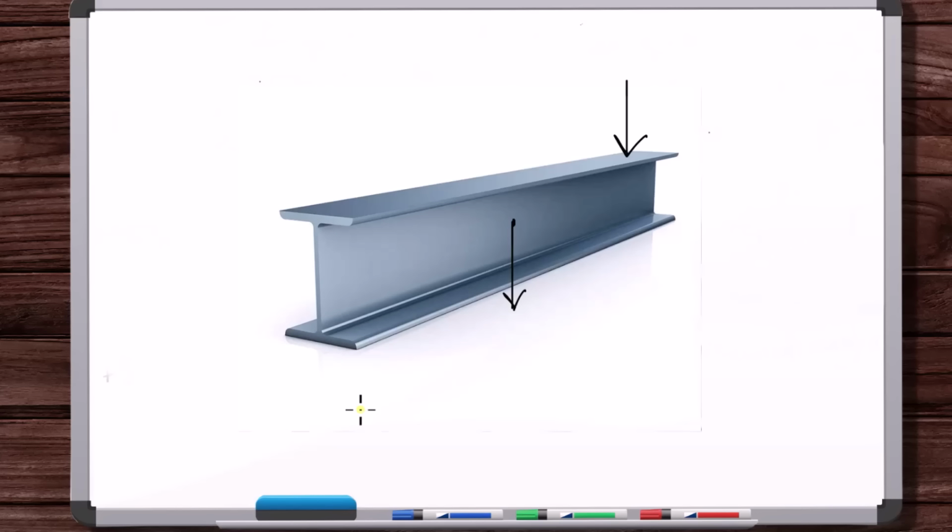Okay, so what's the process we did? We identified points of contact or areas of contact, and then we looked to see, is the size of that area large relative to the dimensions of the body? Well, yeah, this is large relative to the dimensions of the body, because the idea is, if this is a small area of contact, we just put the arrow at the center. We make a point load at the center. But if we made it off center, it wouldn't really matter, right? If we made it a little bit off center, it wouldn't matter anyway.